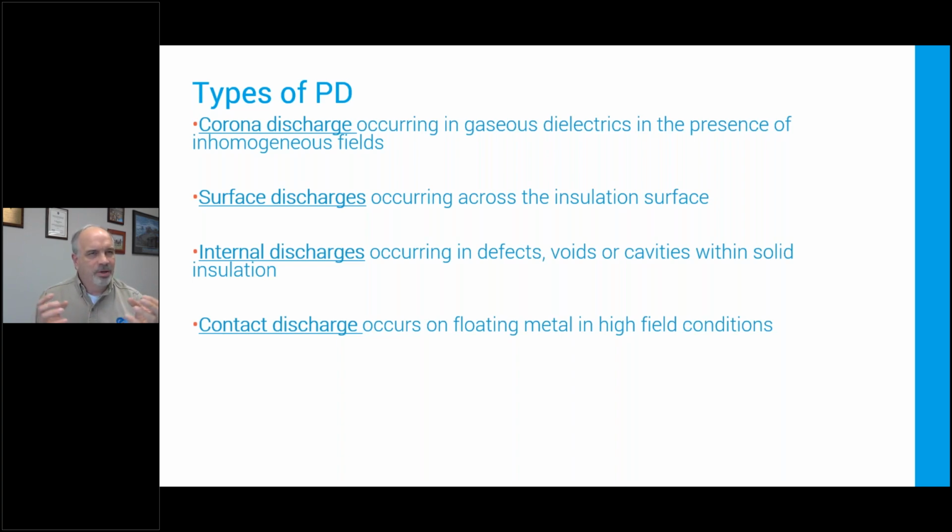We've got lots of air molecules, the air molecules are replaced, and the discharge does not build up, does not cause continuous damage, and does not lead to flashover. It creates ozone, it creates nitrous oxide, it creates electrical noise, it wastes power, but it doesn't lead to catastrophic failure. So we want to be able to identify corona discharge and not mix it up with the other types of discharge that really bother us.